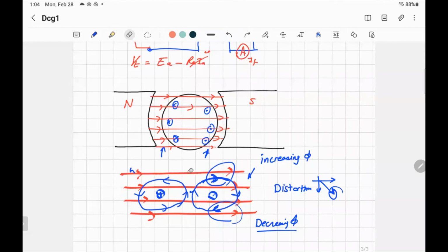No, it's this direction, this opposite, and this one the same. The same thing happening at both. It happened at every single pole in the machine. So the two main effects that will happen are from armature reaction. What does armature reaction mean? When the armature current flows in the armature winding, it produces flux, which affects the main magnetic field in two main effects, demagnetization and distortion.